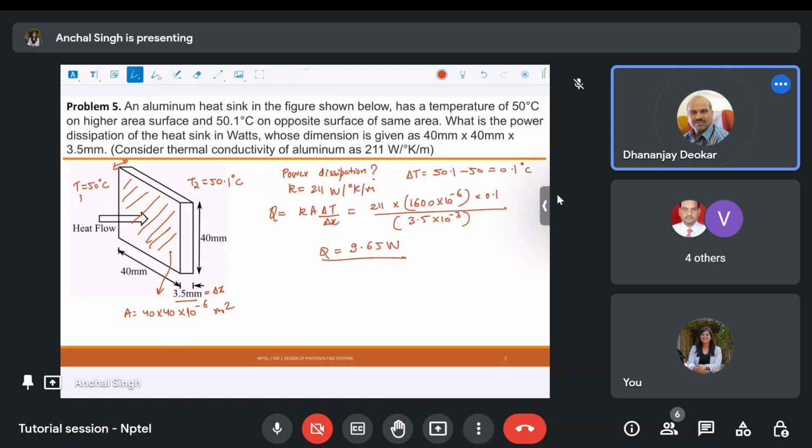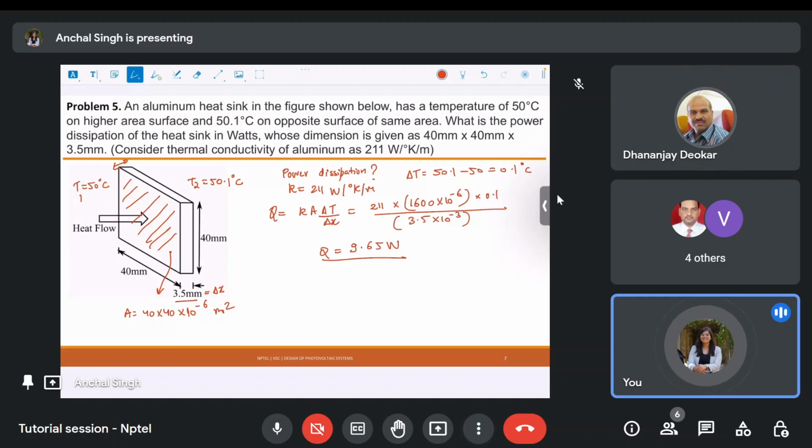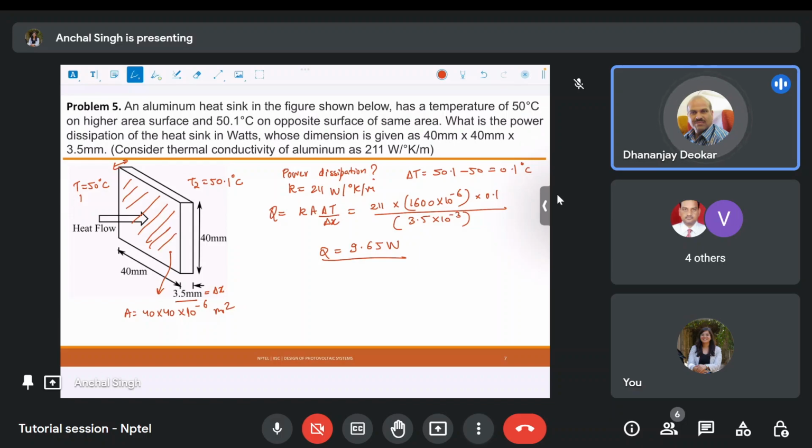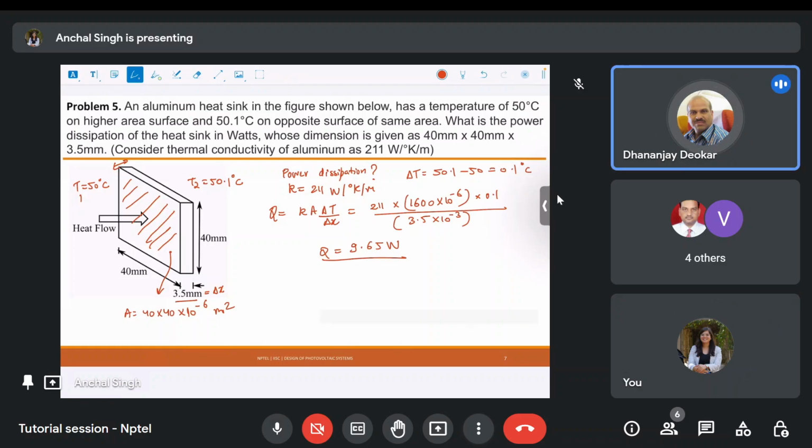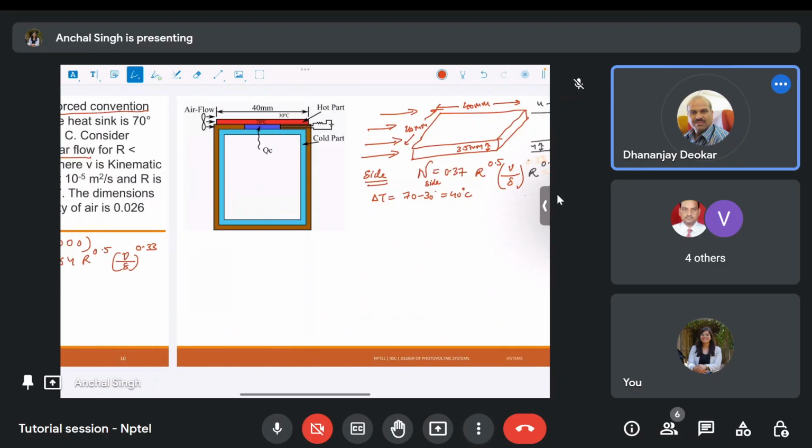Yes, that is the only difference. If it is forced cooling, the number Nu will come in here. And for forced convection, if it is through a fluid, it will also be different. Nu will change depending on what kind of fluid it is, and if we are using a fan, then the speed of the fan will also come into the picture. The number Nu will change accordingly. Okay, thank you.